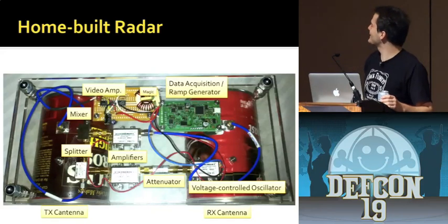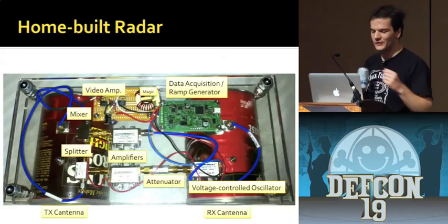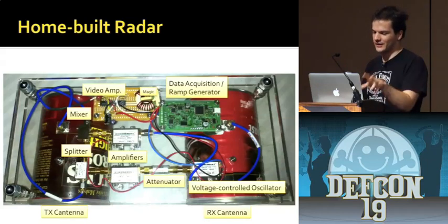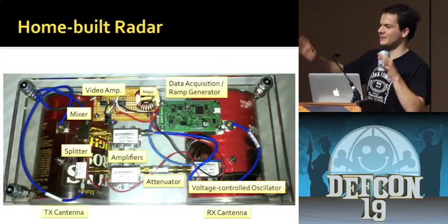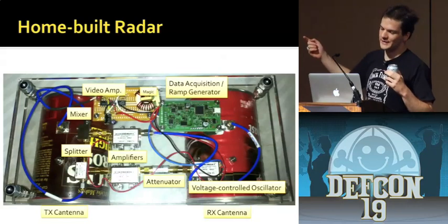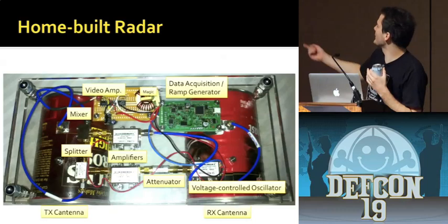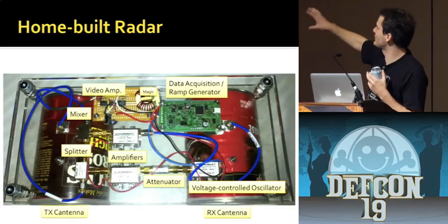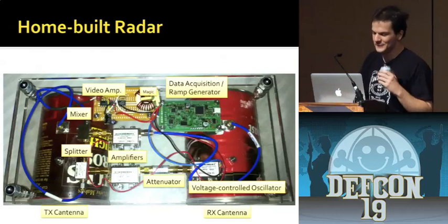So the reason that's there is because when I was trying to make this thing USB powered, I just wired it onto the power for this other stuff. Everything on here runs off of 5 volts. So I plugged the USB in, and the computer doesn't like that. It just turns off the port. The problem was the inrush current was too high, and I needed something to slow that down. So I was like, okay, I'll put an inductor in there. The only one I could find was this big choke transformer thing. So I just shoved that in there, and that worked. So that's all that's for.